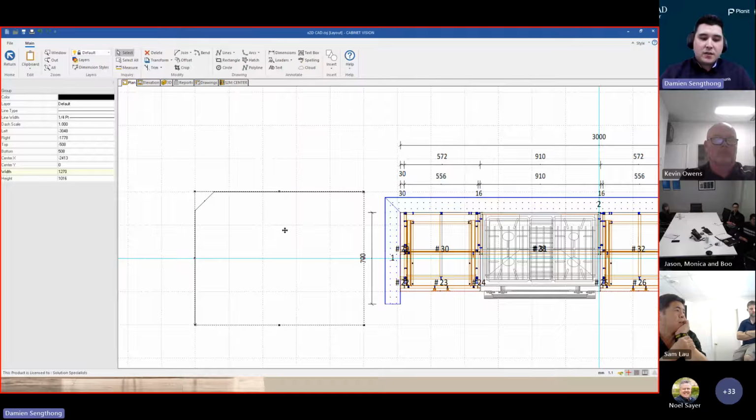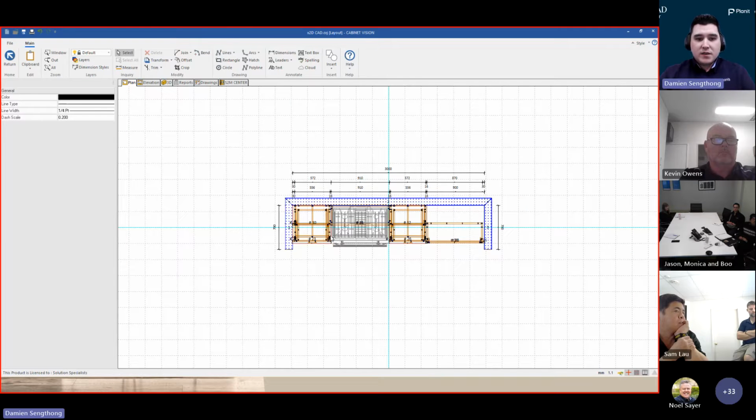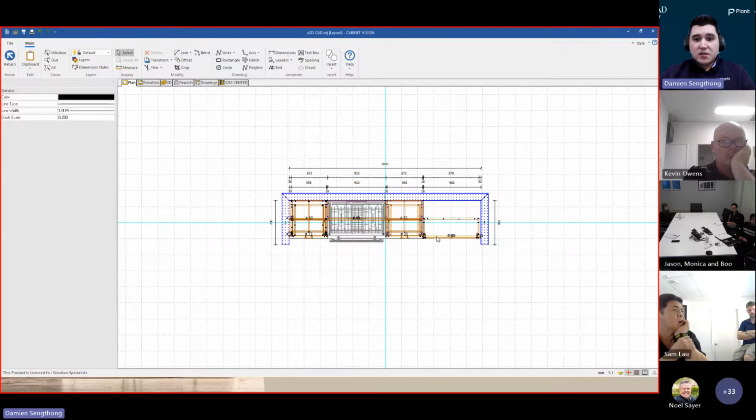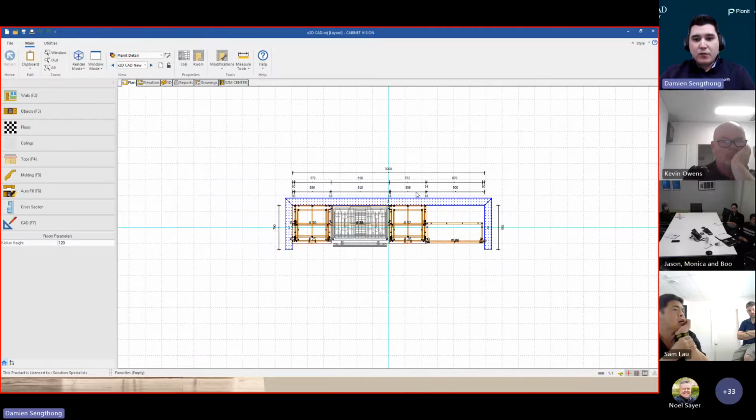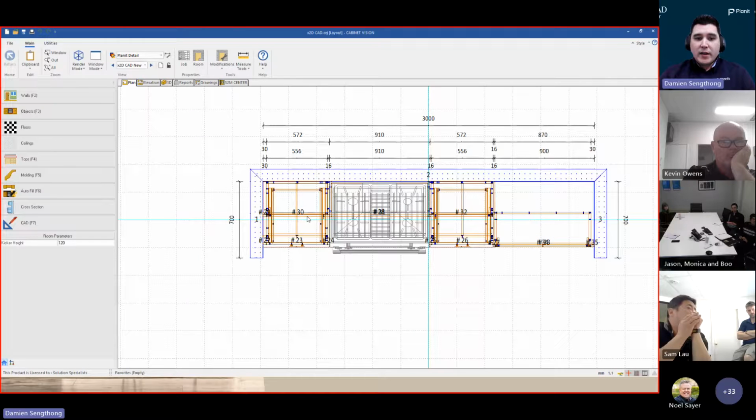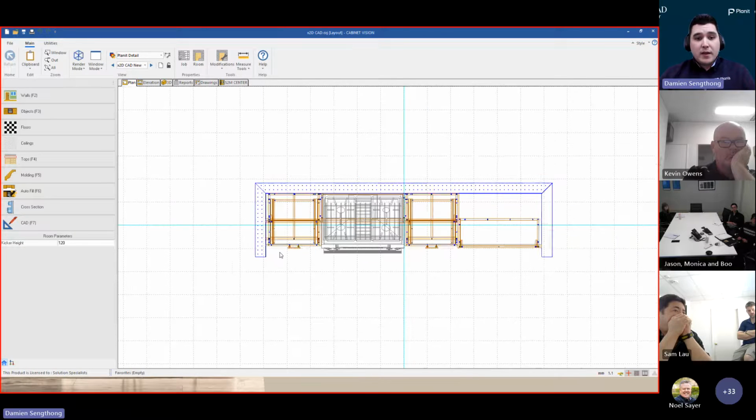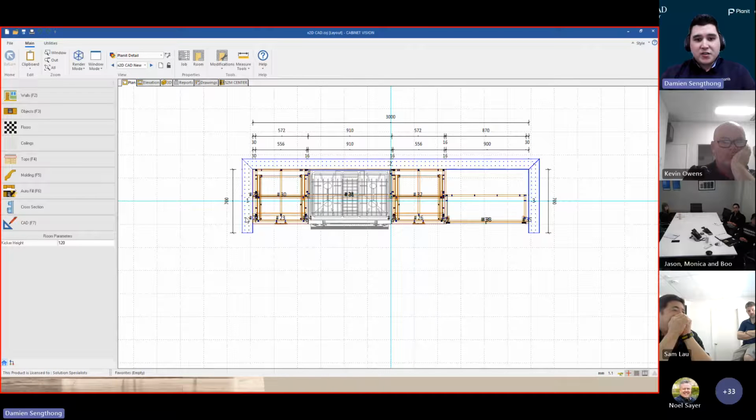So I will just remove these CAD lines now and recenter my page to demonstrate the next function, which is offset. Now, offset's very useful if you already have CAD drawn out, but you wish to copy that line and move it in either a horizontal or vertical direction of your distance. So this is where I'll be utilizing my sample room here. So the way I've configured this room is that I have a bench depth of 600 mil, and I will be using the offset function to locate where I wish to put my island area.